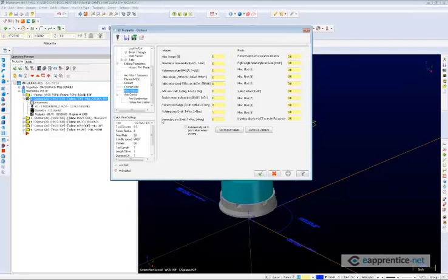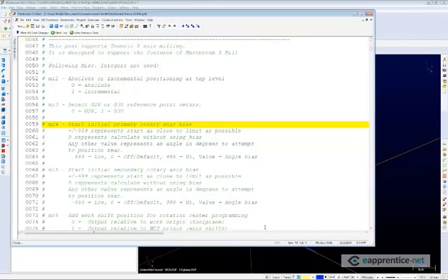So for example, we can take the secondary axis, say that this was a table machine, and it was a Haas VFTR, for example. I know that's a pretty common machine. Lots of people have them. And your table and your rotary axis on your trunnion was rotating towards you so that it was hiding the part from the view of the operator. One of the things that we can set here is a switch. You notice that it says 1 equals POS, that stands for positive, 2 equals negative. So if we wanted to temporarily restrict the secondary axis, and we wanted to say force that A axis to go negative, I might set this to 2, and that would force it to go negative in my output. So we can use these miscellaneous values to control the post. Well, what else can we do?